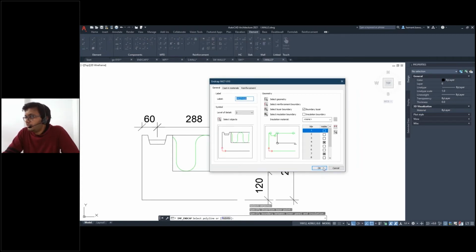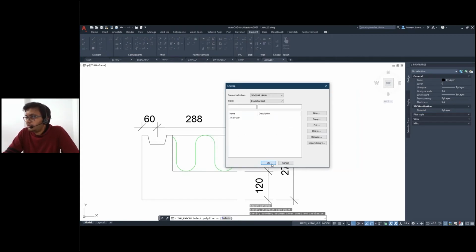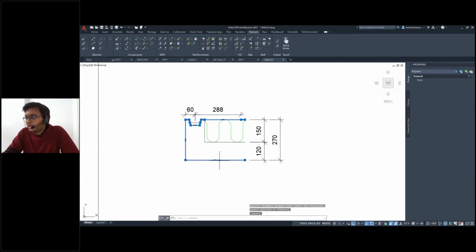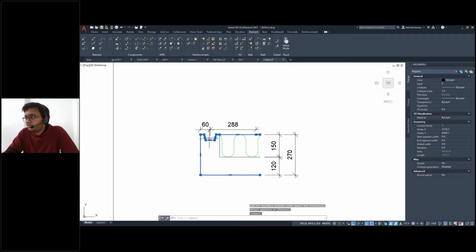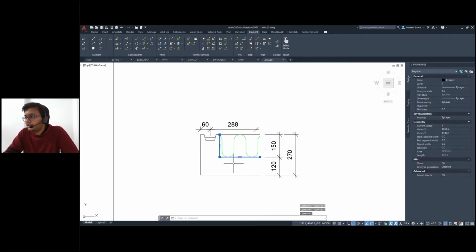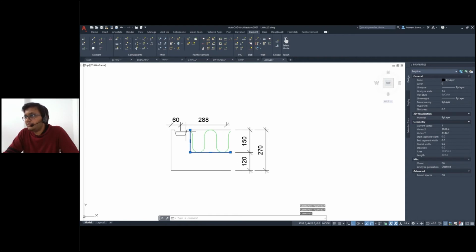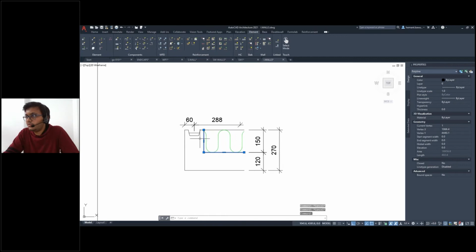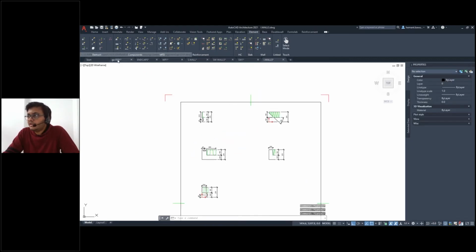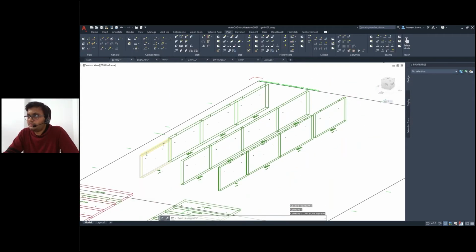You can see. Okay, and okay. Now here before defining, I should tell you that geometry of the wall should be one polyline, and the separating layer between the panel and the insulation should be one complete different polyline. So we can again apply the same thing in here for this our insulation wall.